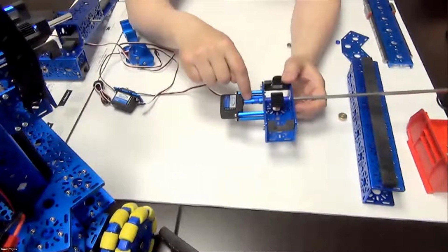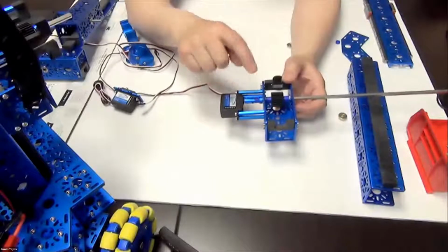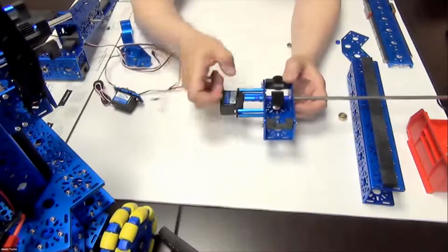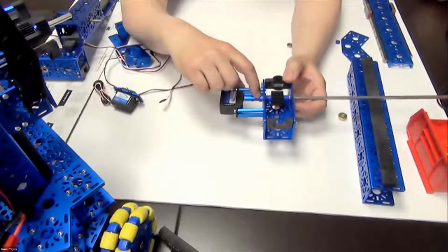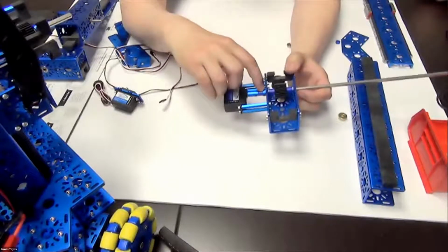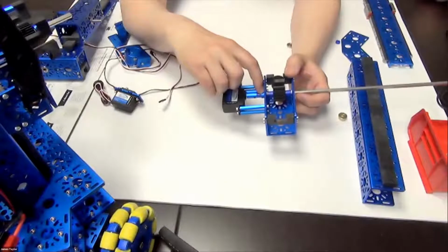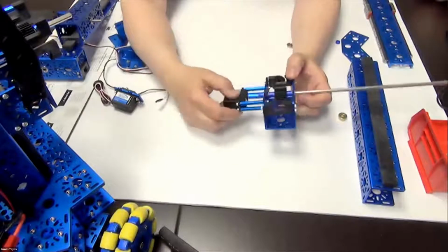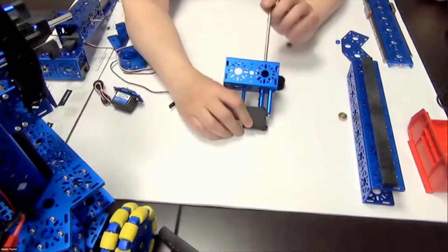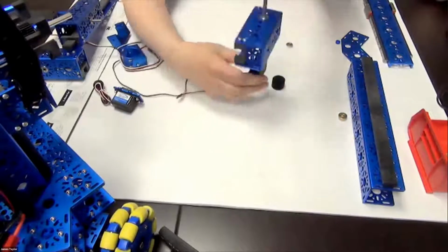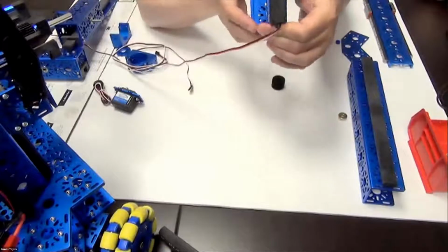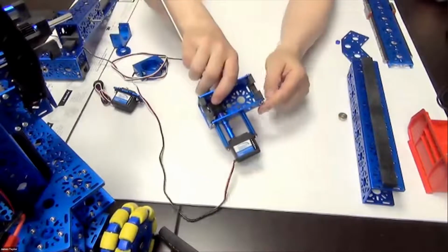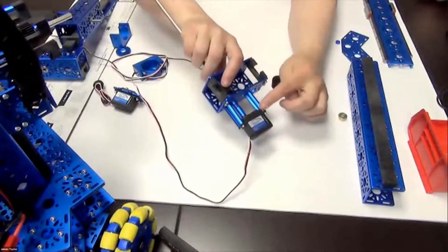Right here, he's got the servo to shaft adapter. He's got a couple of spacers so that there's no movement. And then he has the collar clamp here, mounted up to the bearing, and I'll talk about that in a little bit. But if you actually look at this from different angles, you'll see that these are beginning to twist inside of here, and you can actually see that these are beginning to be crooked.